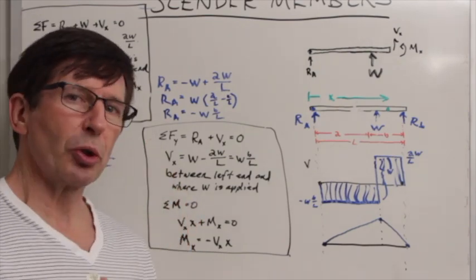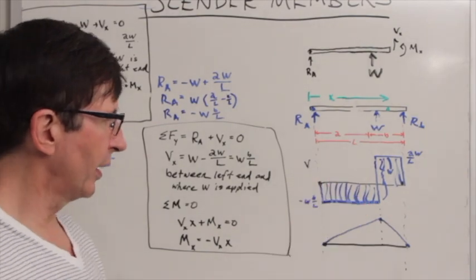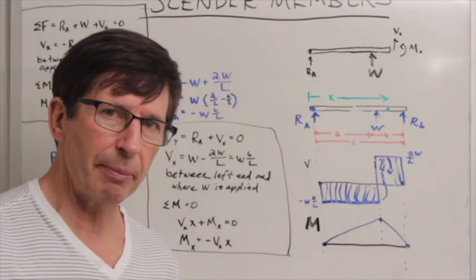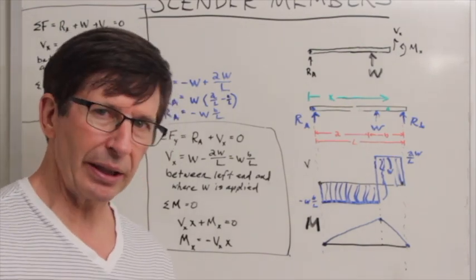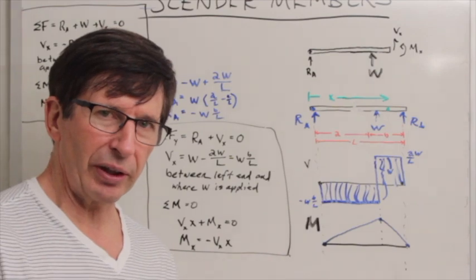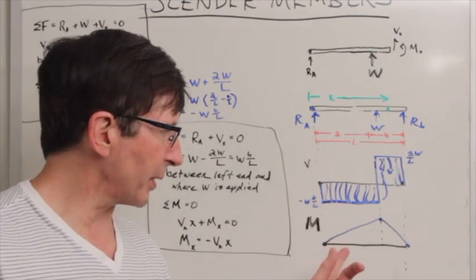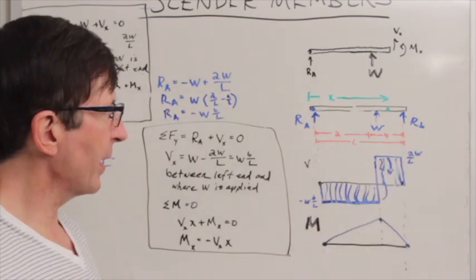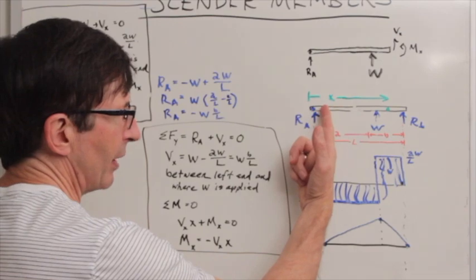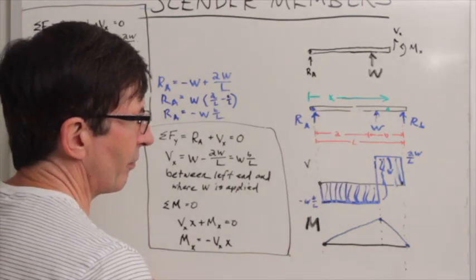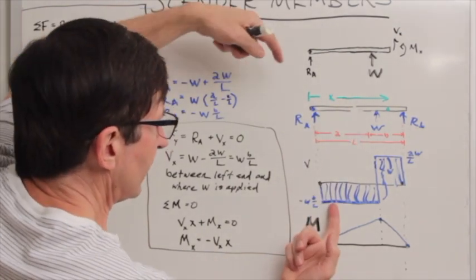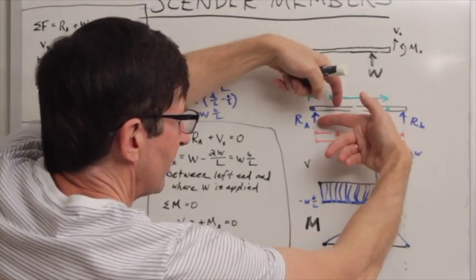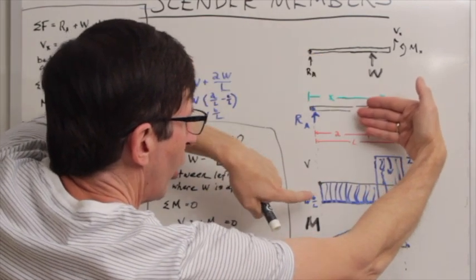And now we are going to plot what are called shear and moment diagrams for this beam. And this is a very common technique. And if you take the fundamentals of engineering exam, you will need to do shear and moment diagrams. Here we plot the shear from the left end to the right end. And sure enough, if we're thinking about the shear in the beam, we need a reaction as we're moving our way across at this end that's opposite to RA.